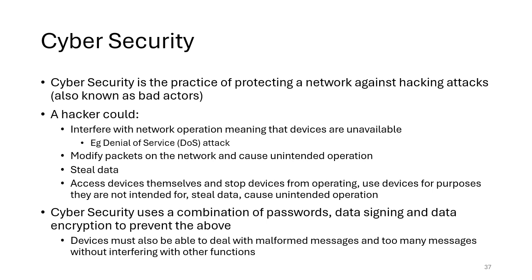If someone was on your local network, of course, that's a different story. So you also need to think about how you are going to protect your network from internal bad actors as well as external ones. Now, people might want to steal data. Again, maybe they're not trying to write to your devices, but they may be able to pick up that data. Understanding what's going on inside those Modbus packets might be enough to understand what the throughput of that machine is. So you might understand, is that company producing today? Based on what they're producing, how many orders have they got? Is the machine running flat out or is it idle? That sort of data could be useful to a hacker or particularly a competitor who's trying to understand what you're doing.